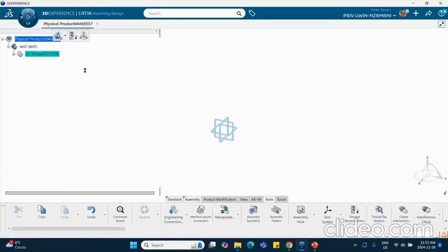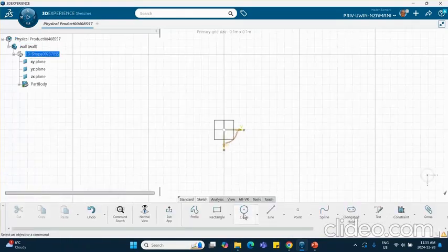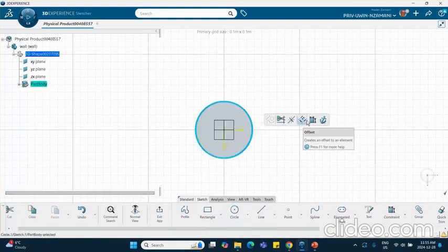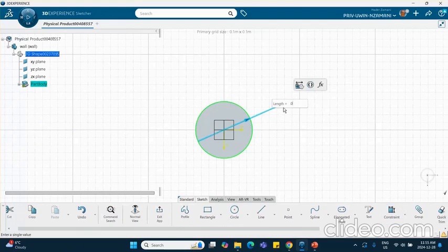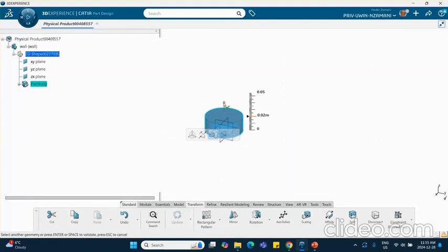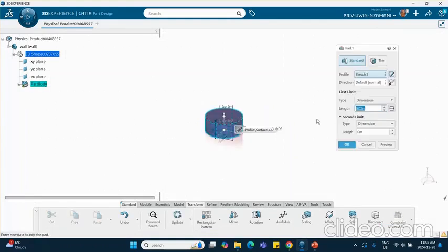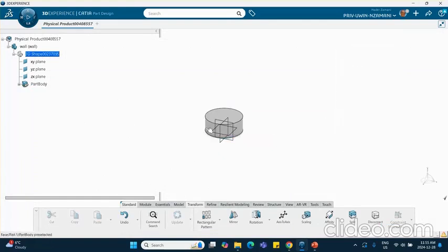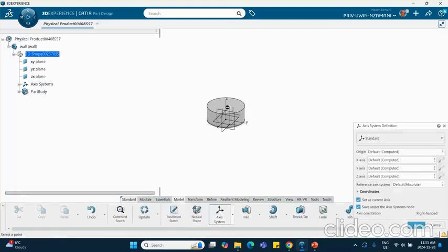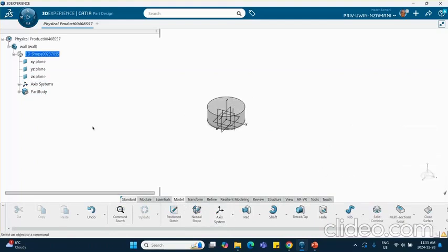It's just a cylinder. Double click on it. On this plane, I will sketch a circle of radius 0.05 meter. All right, exit. And pad it by some amount. For example, let's make it, it really doesn't matter. I'll make it, yeah, that's fine. Now, what I will do is I will create an axis system here while I'm at it. Okay, let me create an axis system. Under the model, the axis system is going to be put at the global origin, which is there, and that's fine. There's no problem there. I'll just leave it the way it is.